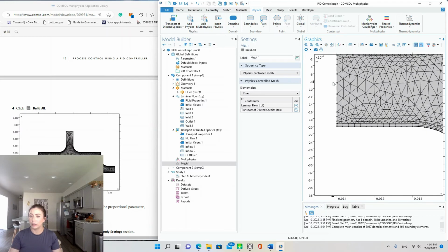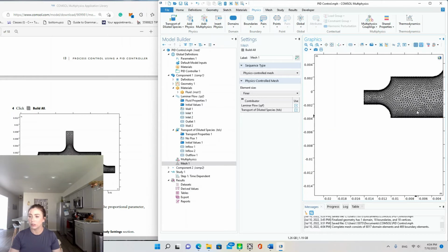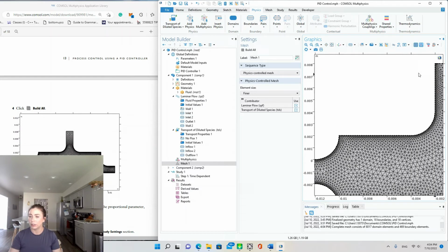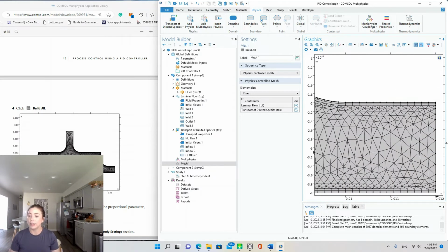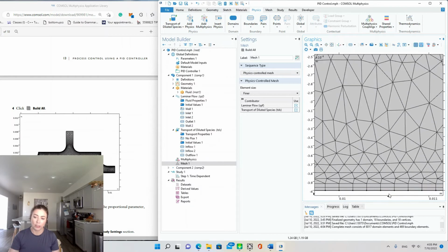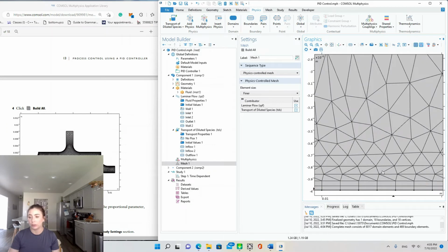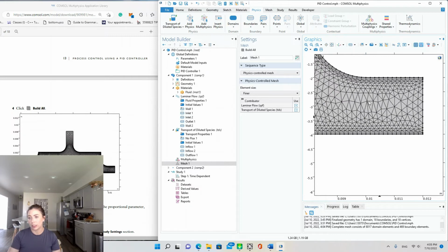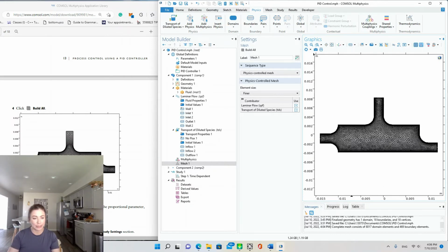And then past that boundary layer, it uses triangular elements. Okay, let's look at the inlet. So what are inlet and outlets? It uses triangles even on the edges, and all other boundaries not specified as inlets and outlets have a boundary layer of 2 rectangular elements and then triangular elements becoming larger as it approaches the middle. Zoom extents.